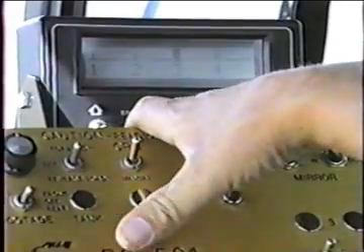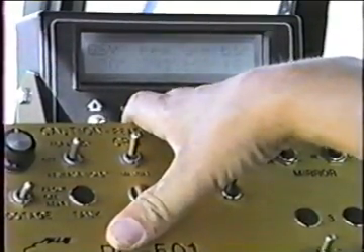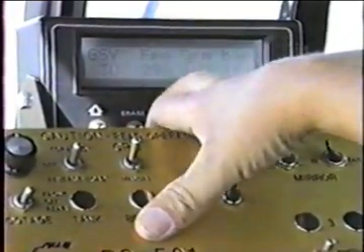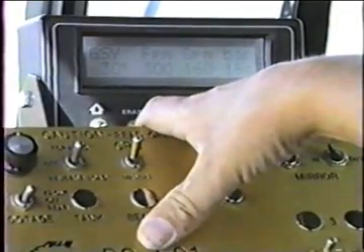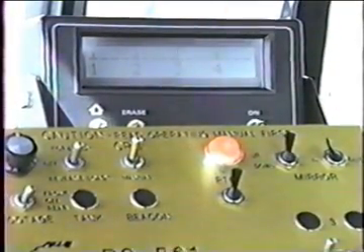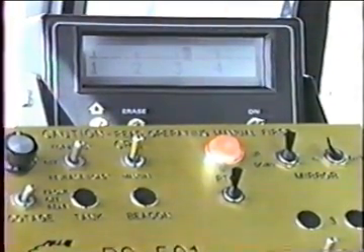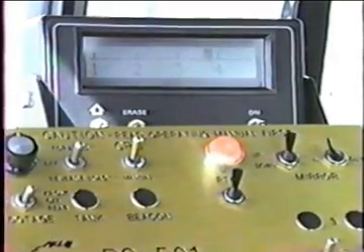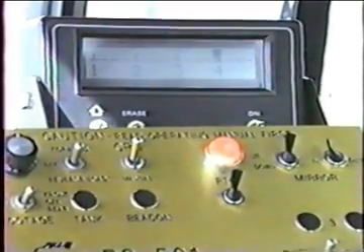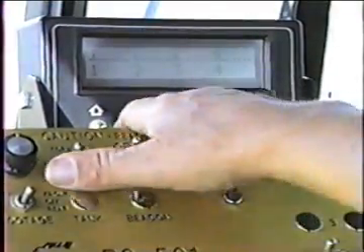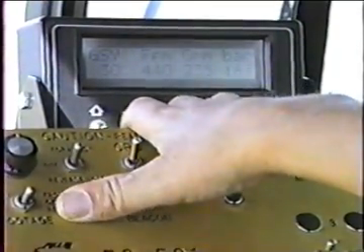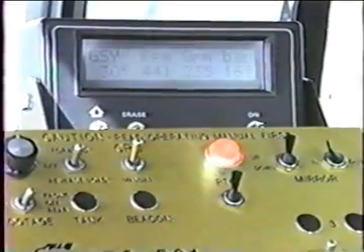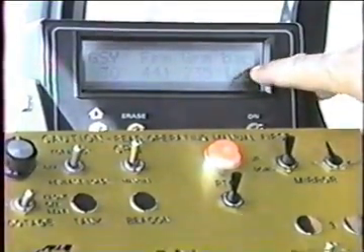We can take a look back over here and see how fast we're going. We're at 299 feet a minute. That's the ideal speed for number 3 nozzles. If we had number 4 nozzles in it, just a matter of speeding up. That's the ideal speed for number 4 nozzles. Taking a look here, and now we're at 440 feet a minute and 0.3 of a gallon to the square yard. Again, you see 4 tick marks over here.